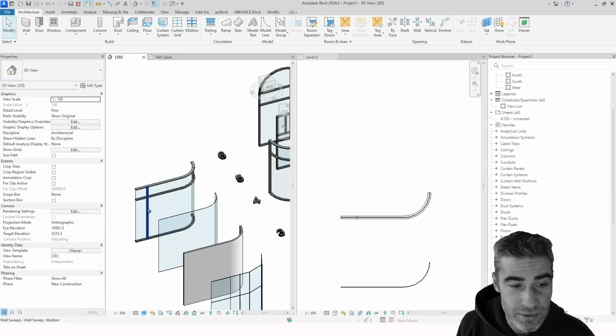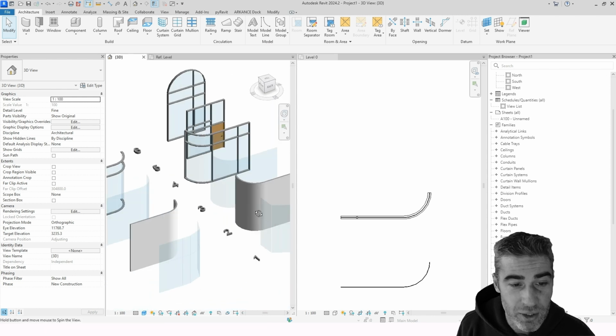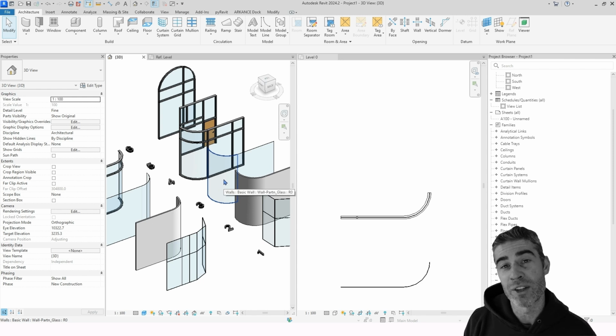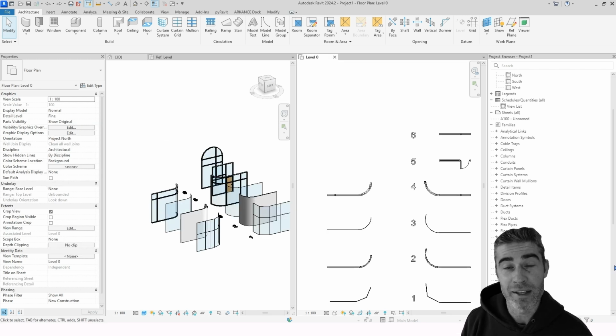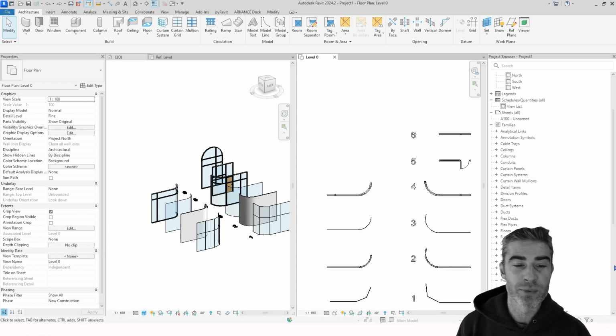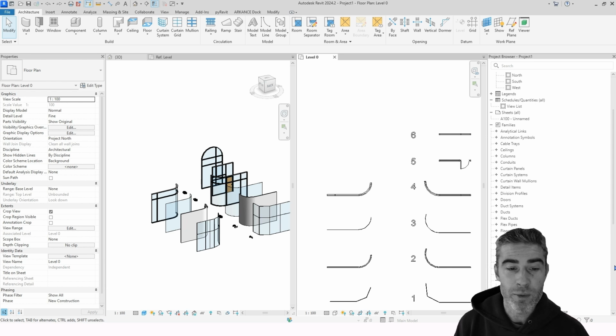And you can add these verticals to your start and end point. So this way, you're getting a curtain wall, but not using your curtain wall tool; using your wall assemblies and creating sweeps and mimicking and getting them to look like a curtain wall. Now you're at the point where you've realized that there is a different approach than utilizing curtain walls. With curtain walls, you can achieve something similar, but what happens is it gets more complex.